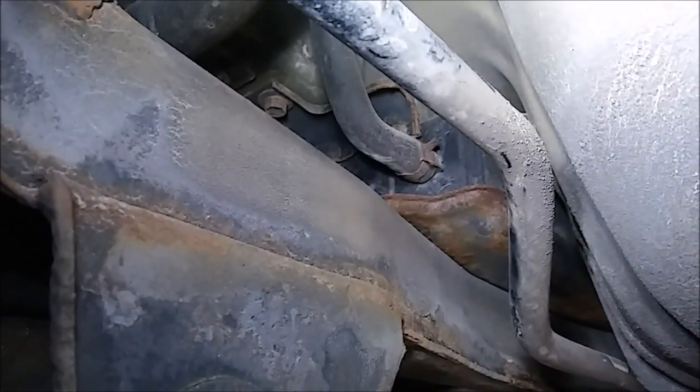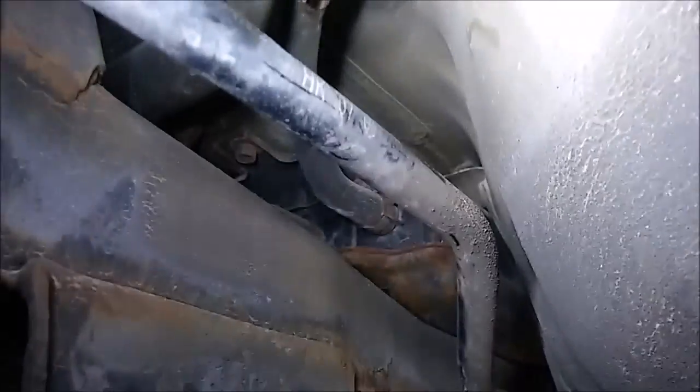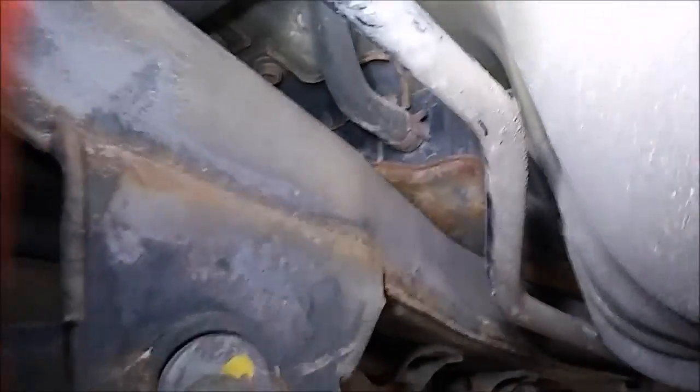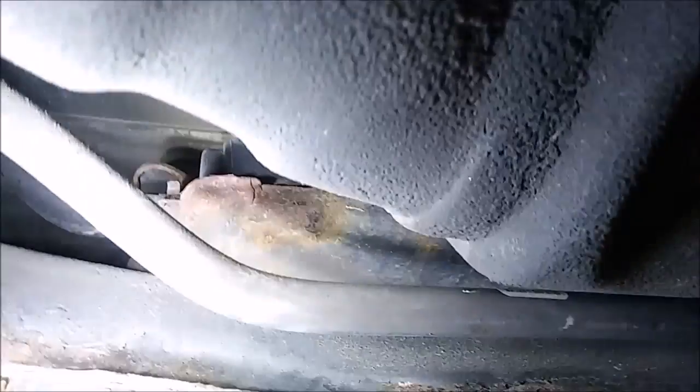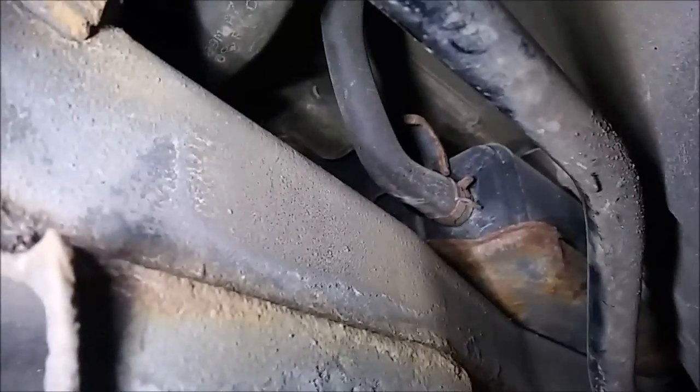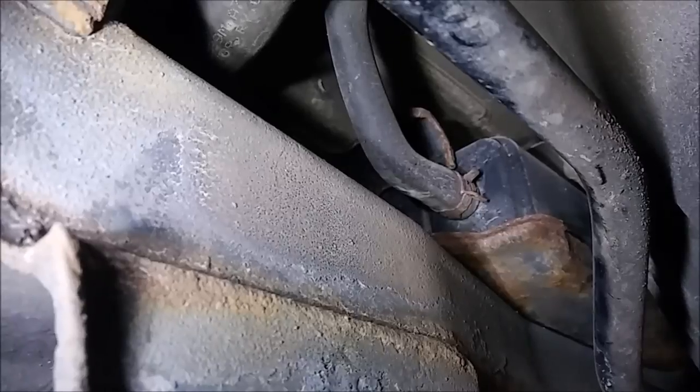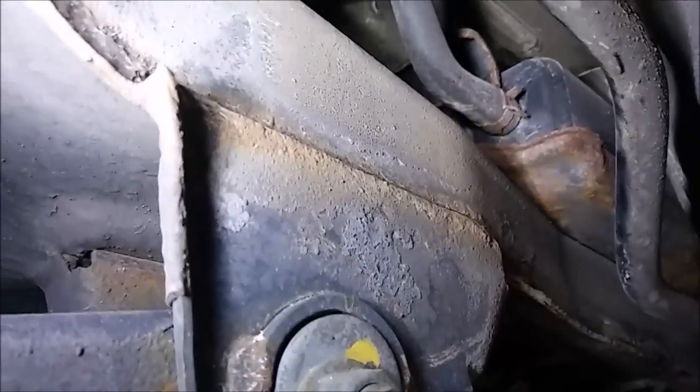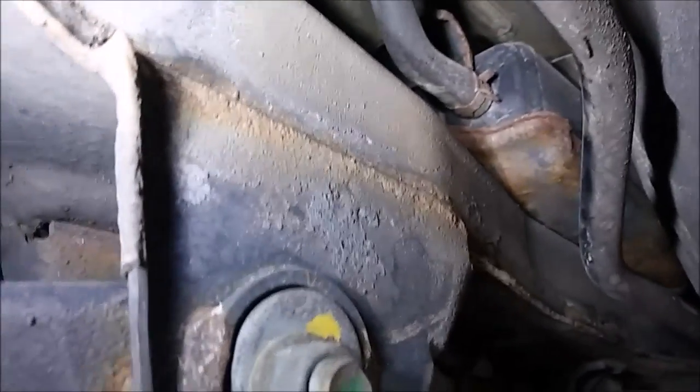But basically the area that this is coming from is, if you look at that hose right there, if you look to the very bottom of the canister, it looks like it's coming from the bottom of the canister, maybe underneath this mounting bracket here, above where this sway bar is. We can see a little bit of rust up here. But this canister is definitely leaking. I can't see exactly where from. It's from somewhere underneath it.